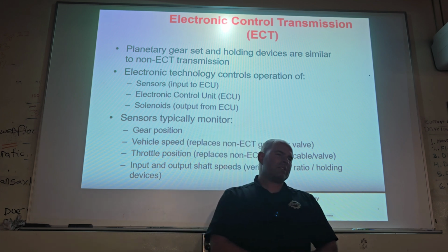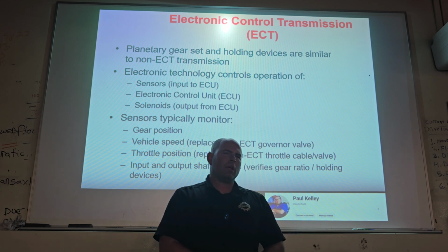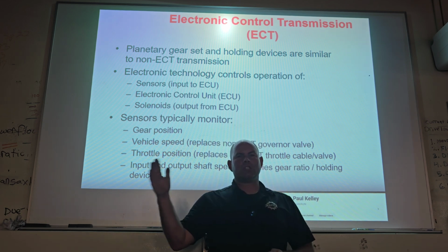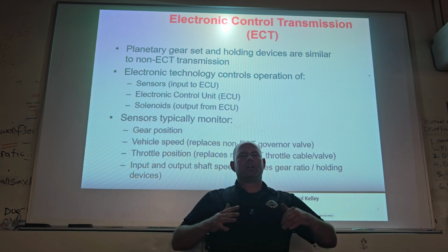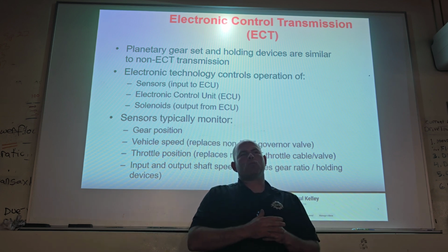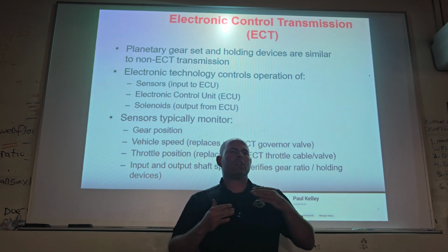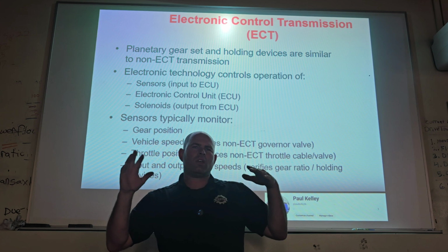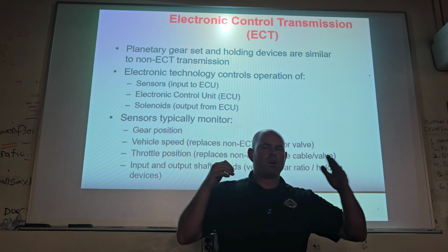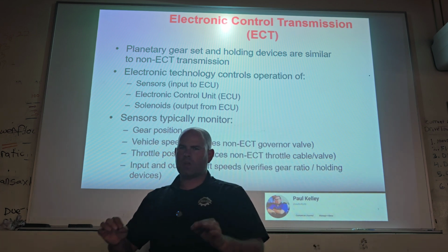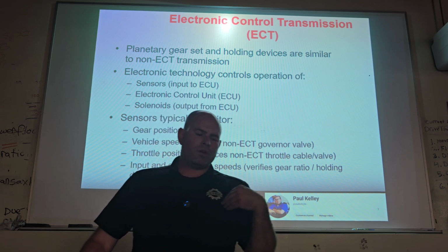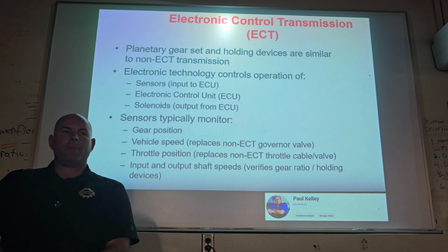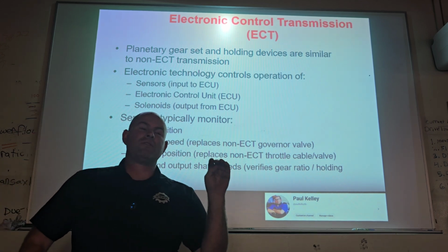Technically, you couldn't as a technician, but if you wanted to be a tuner and you went into that table, you could adjust those values and change your shift times, and you would basically rewrite when the shifts occur. You could give a little bit of an advantage to throttle, and that way it delays all your shifts. You could give a little bit of an advantage to governor, and that would make all your shifts a little bit earlier, right? So you can go in and fine tune that. Typically, we don't do that. Who do you think does that? The tuner would do it after the fact.